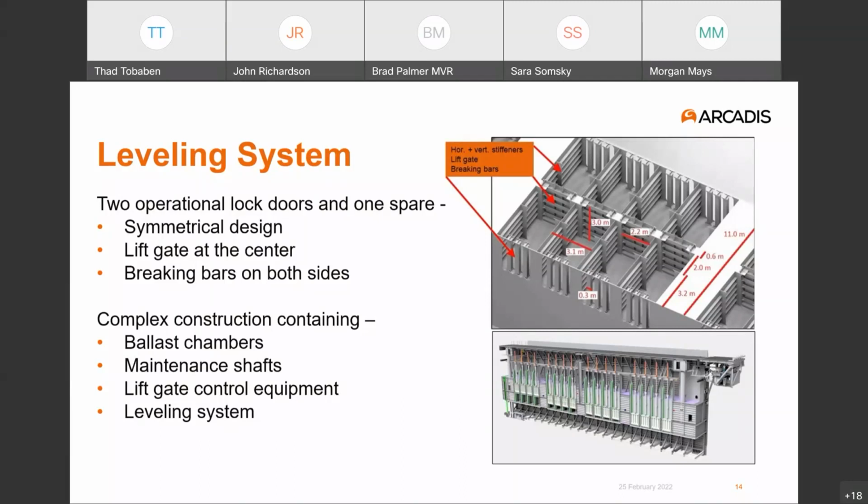Then these jets or high-speed flows will move into the lock, and if they persist for a great distance, then if I have a vessel that's moored in the lock, that flow will exert a force on the vessel, and in order to keep the vessel in place, I'll need a mooring system that's adequate for it.